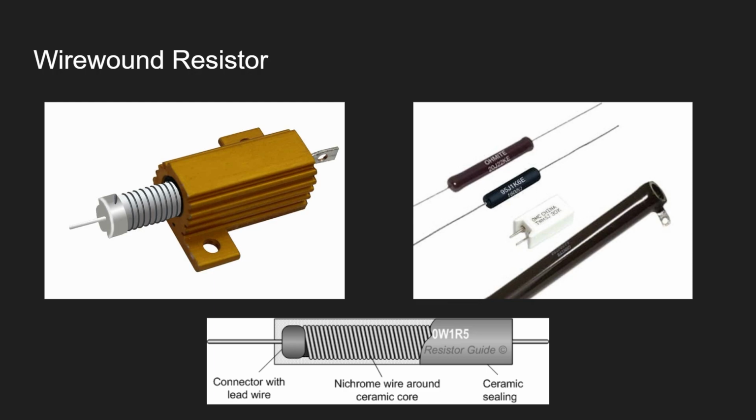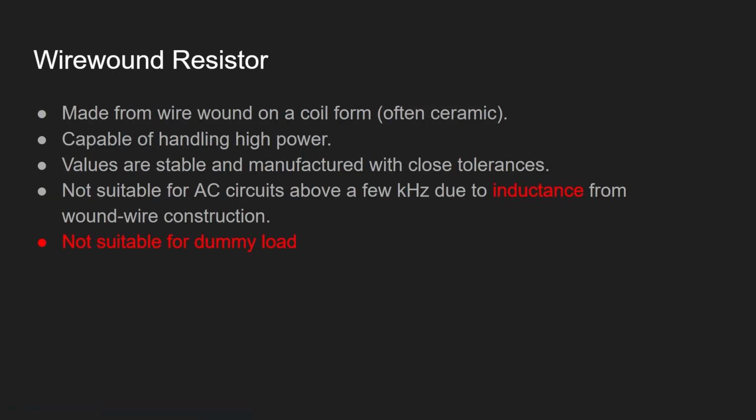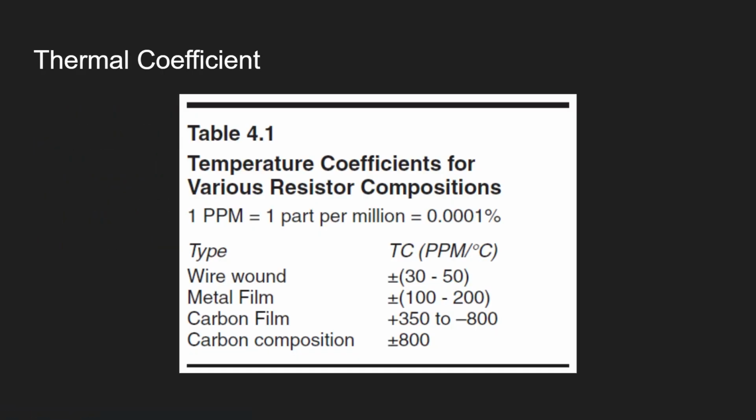It is a different story for audio output. It won't interfere with your radio, and you can use what you want. Wire wound has a very big advantage: it can withstand a high current compared to metal film or carbon composite.